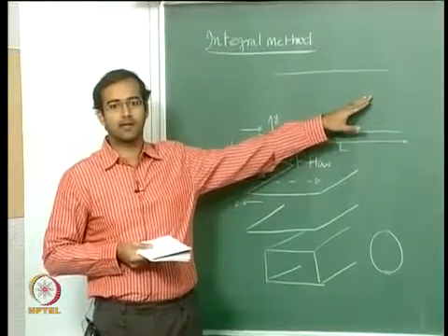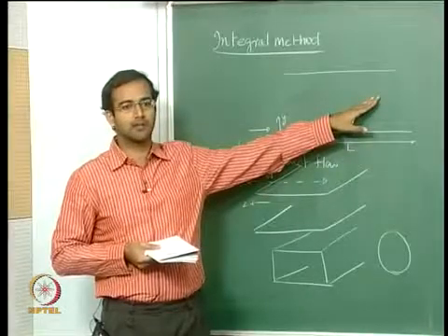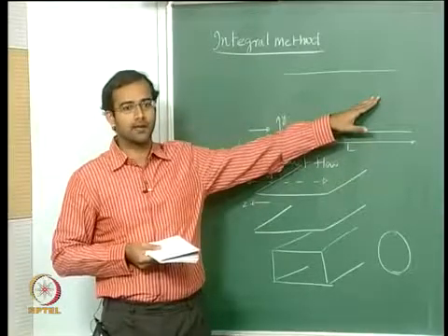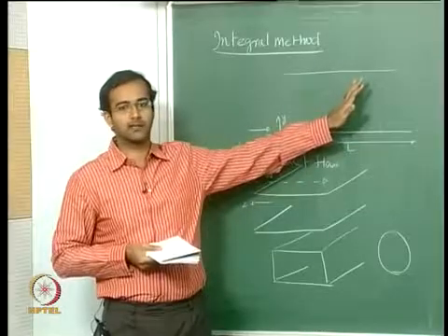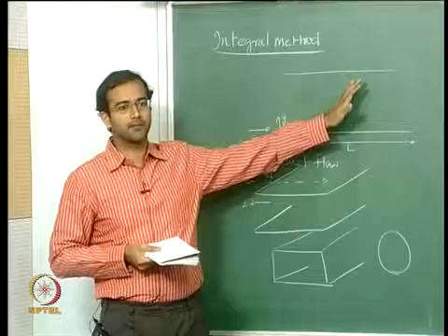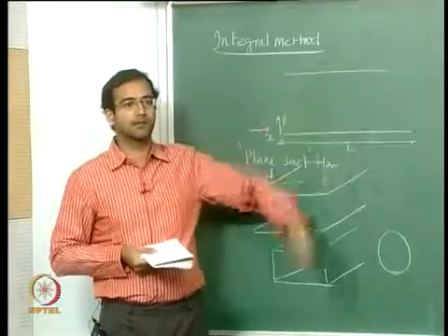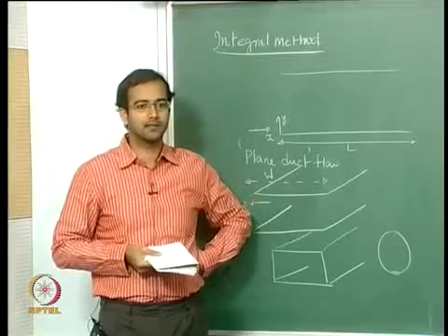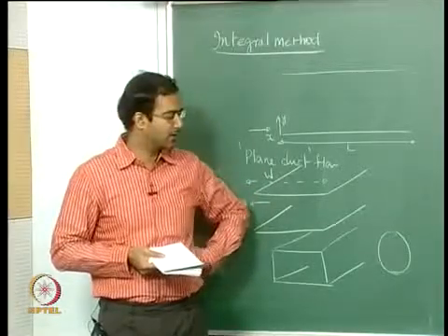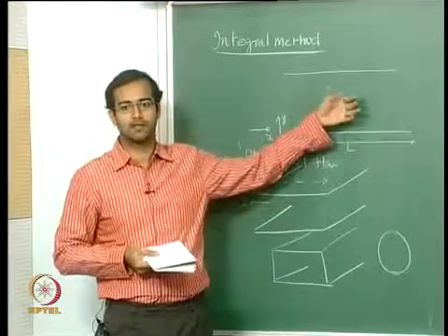We neglected the radial and the tangential components. The radial component was included in the conduction part, of course, but when we looked at the energy balance, we neglected the dependence on the theta direction, the azimuthal direction. So strictly speaking, what we considered so far were 2D axisymmetric flows.